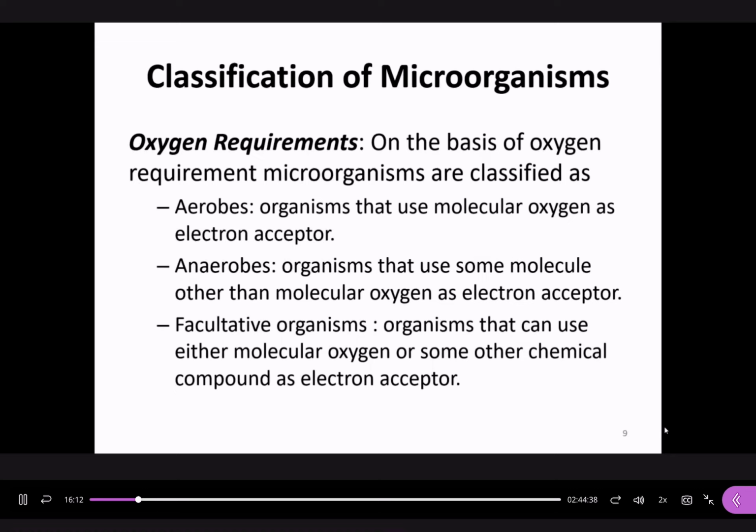This is the product. So what happens in wastewater treatment? Wastewater organics are converted into CO2, and you need oxygen to accept the electrons. This is the oxidation reaction, and that is the reduction reaction. You need oxidation as well as reduction. You have wastewater organics and oxygen, and the product is CO2 and water. But that reaction happens with the help of microorganisms, and that is what happens in biological wastewater treatment.